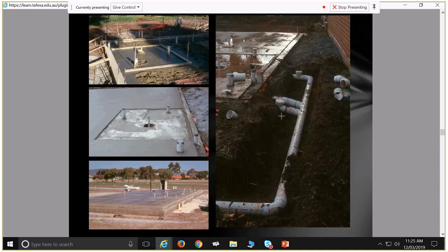So I don't expect you to understand set downs and bathroom design and things like that straight away. This is something you've got to learn over time, but in essence, that is something that has to be planned for initially. So when you're specifying your slab, you're thinking about your set downs, you're thinking about the slope relationships in your floor, where you're going to have a floor trap, if you're going to have a floor trap, etc.